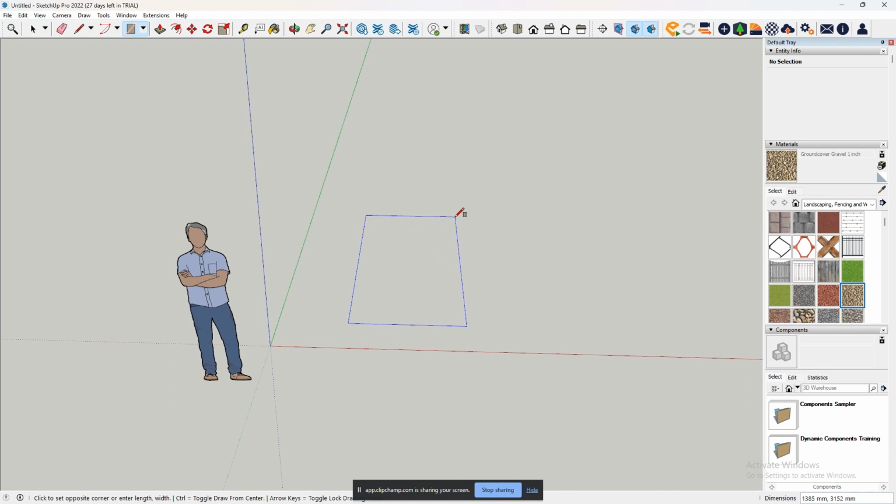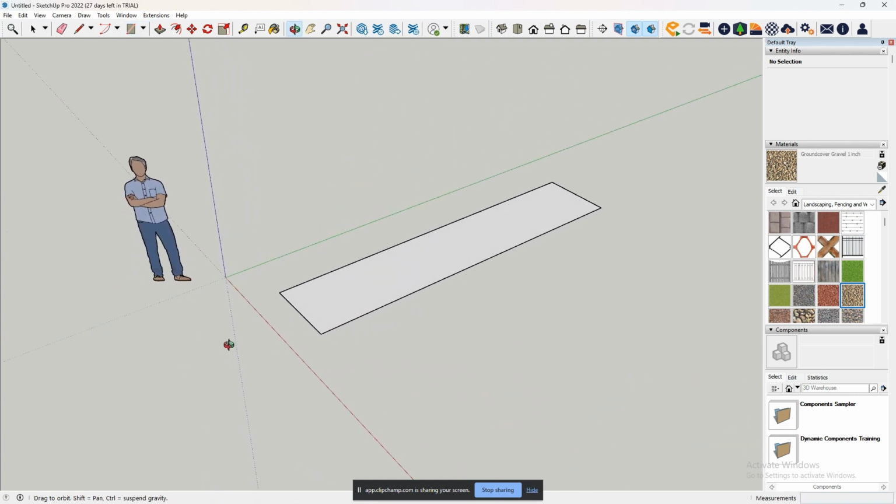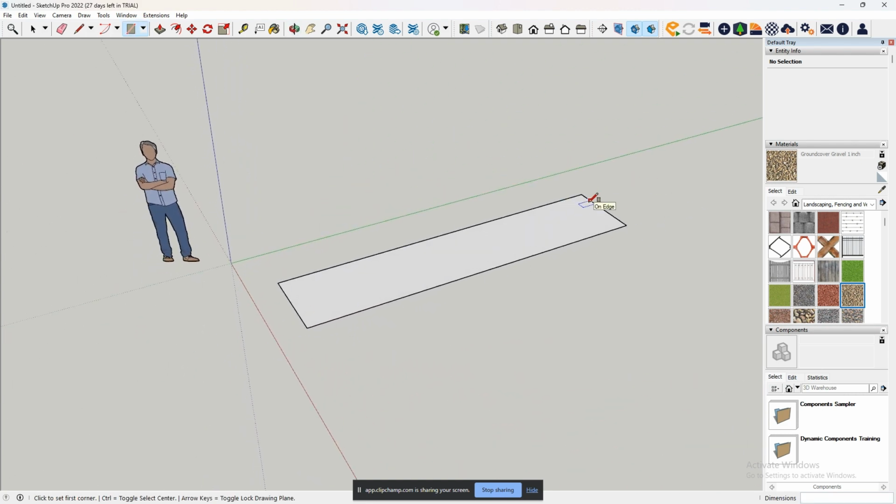And if you look at the bottom right hand corner of the screen, it'll show you dimensions where you can actually type in. You can click it normally like that, or if you want to make it more accurate, you can make it any dimension you want. So for example, 1000, comma, 5000, enter, and it has calculated what those dimensions would look like.